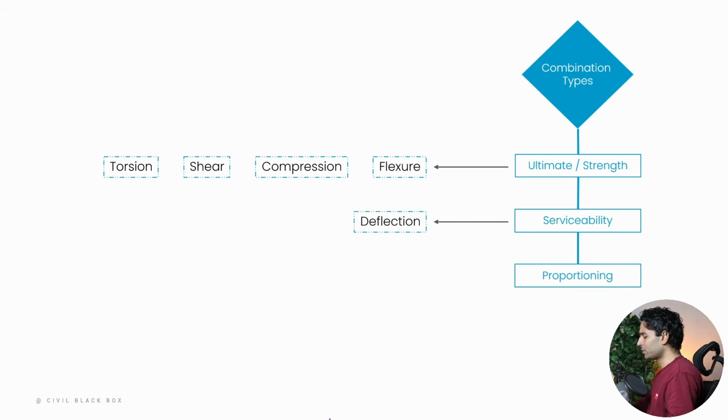When we are talking about serviceability, we are actually talking about the criteria of deflection as well as cracking. Now, this criteria is a bit different. For the serviceability, our load combinations have a smaller factor, and for the ultimate, you can understand that we have a greater factor, because right here, we are trying to understand the limits of failure of our structure. Right here, we are trying to understand the limits of serviceability or life of the structure.